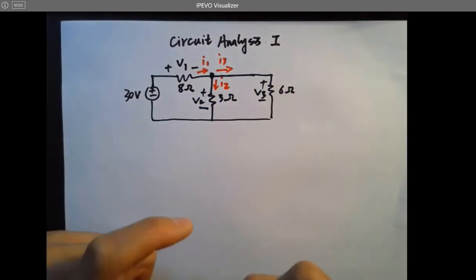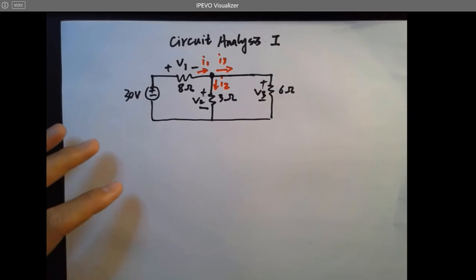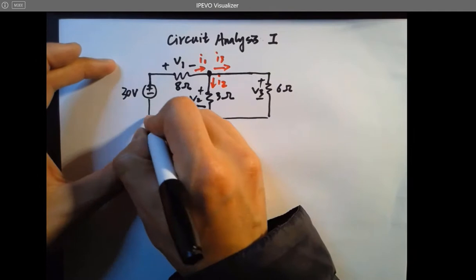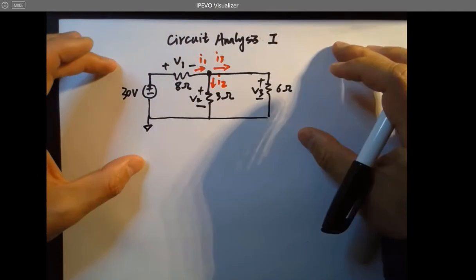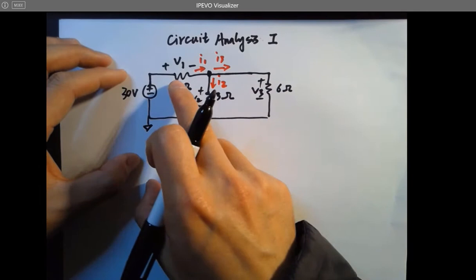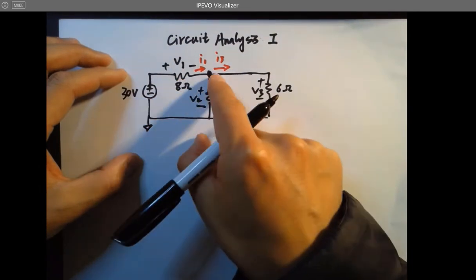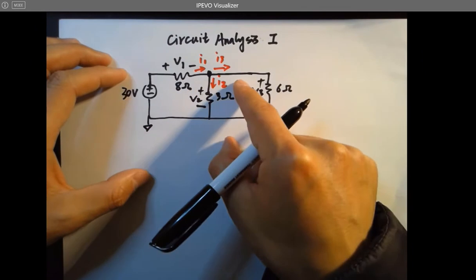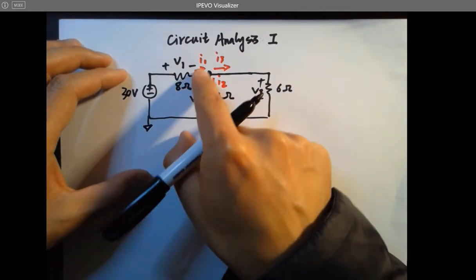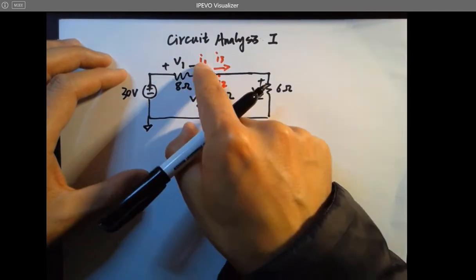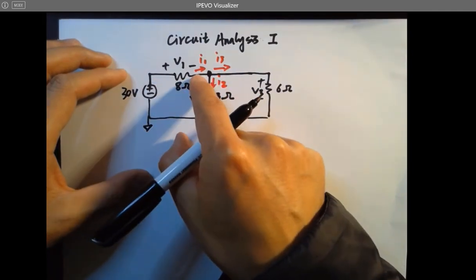Okay. So the purpose of circuit analysis is to solve this linear circuit. Solving a circuit means you want to know what the unknown currents and voltages are at every single place in the circuit. For example, I labeled the currents I1, I2, I3, but I don't know the value of this current actually, right?